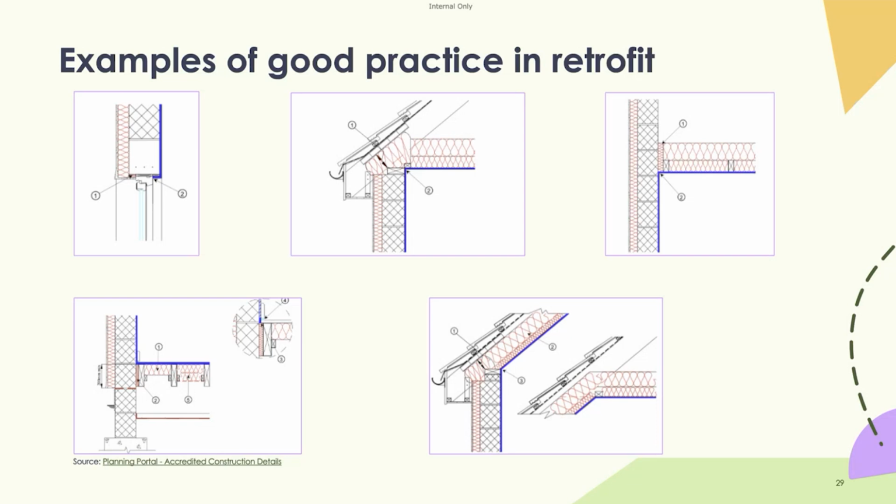We've got a gable wall detail on the next image there. So again, you can see how there's insulation pushed up right against the wall. So you've got 2 layers of roof insulation, and then that final perimeter insulation, just to make sure that, again, that continuation of insulation right up to the wall. And I've got some more examples there of a ground floor junction.